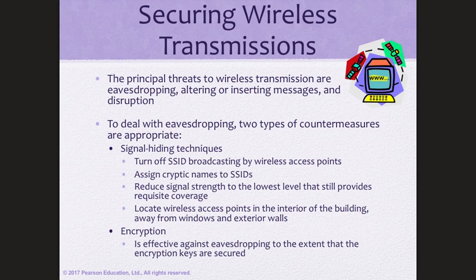Now again, hiding the signal from like a physical layer, actual signal point of view is challenging. One of the techniques used is, for example, use very low power, spread across a very wide frequency. They call that code division multiple access or spread spectrum communication. Okay, so let's say your signal has a power of 1 watt. Of course, this is a very large amount of power for communication.